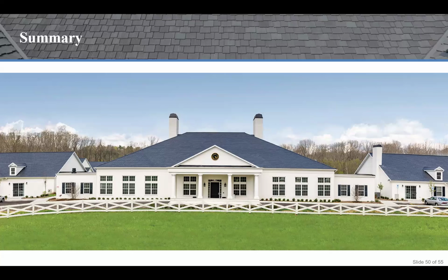Unlike the man-made look that other products might have with one single width, multiple widths provide that random pattern that adds visual interest and heightens the design of the roof. When you compare it to traditional roofing materials, composite provides numerous advantages, such as no freeze-thaw issues, Class 4 impact rating, durability, and color fade resistance. In researching composite roof products, there are several tests that are of concern. This includes testing wind uplift, fire testing, impact testing, accelerated weathering, and freeze-thaw.